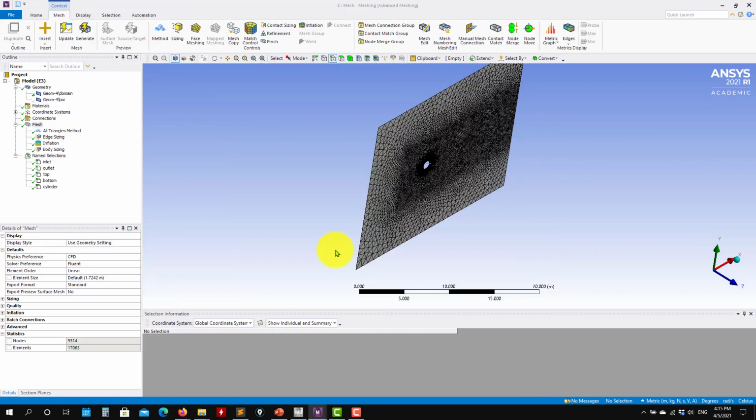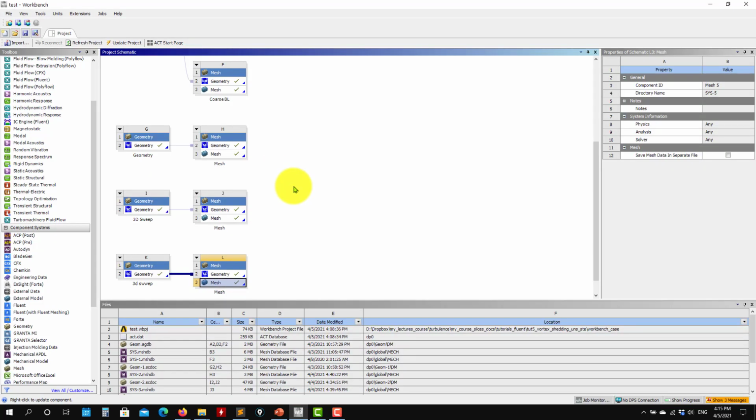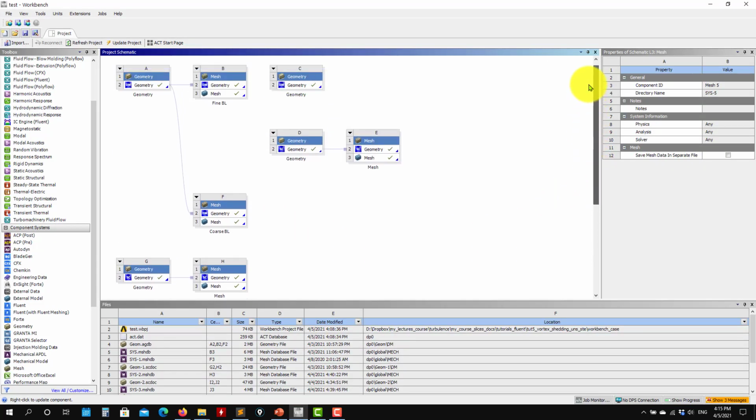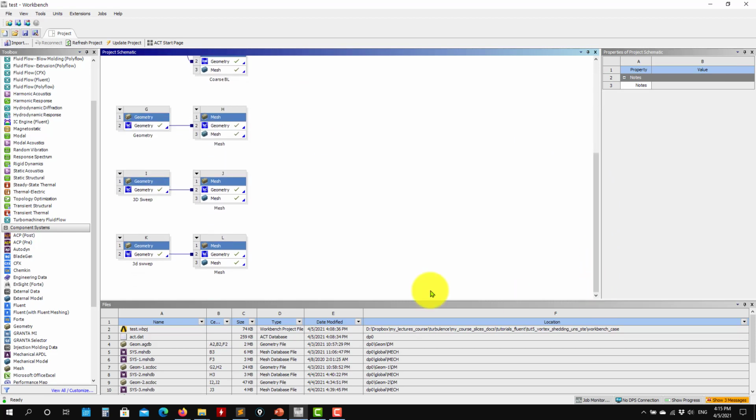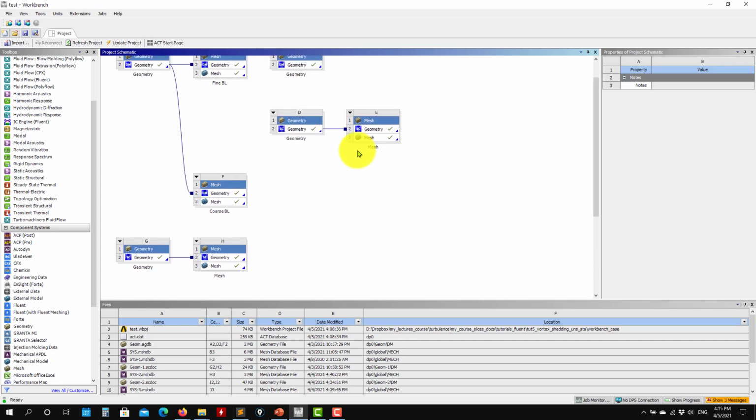So we saw two techniques now to generate the mesh when working in 2D. In 3D, we have seen that there is no need for this. So we can use the fully 2D geometry in a surface, or we can move to the volume, but using a sweep. So this is all for the meshing stage. Next video, we move to the case setup. So for case setup, I will use this mesh. But later I will also show you the difference with the 2D mesh.